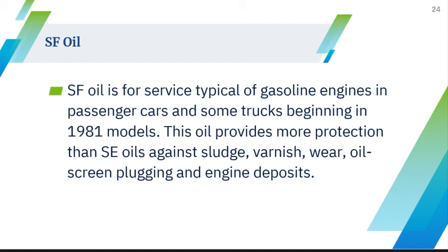SA and SB oils are not recommended for use in automobile engines. These are non-detergent oils. Detergent oils are required in modern automotive engines. Diesel engine oils must have different properties than oils for gasoline engines. The CA, CB, CC, and CD ratings indicate the diesel service classes.